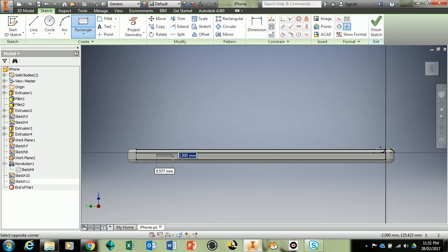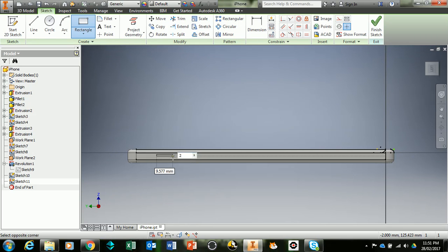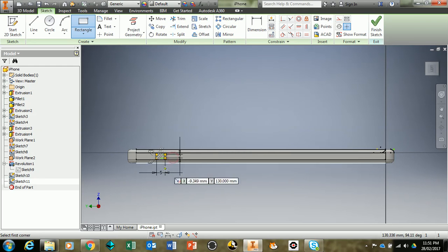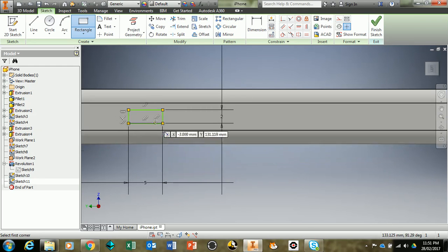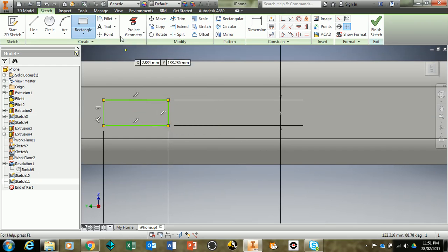and then we're going to build our little rectangle. You could free draw it, but again, we've measured this properly. So we know that the trench is going to have a 2 millimeter height, and then we're going to go 5 millimeters across. Okay, so that gives us a little trench for the button. That's where the button's going to sit.